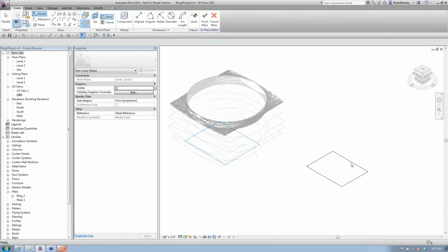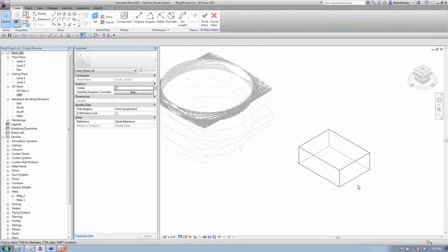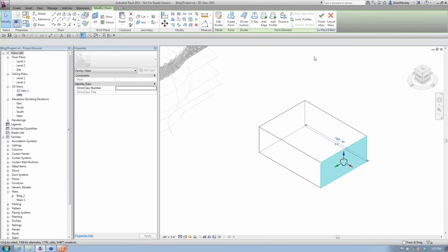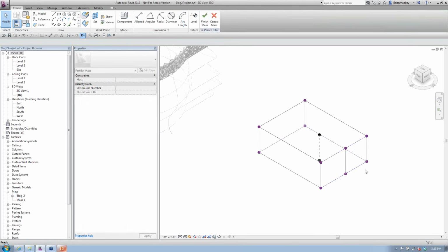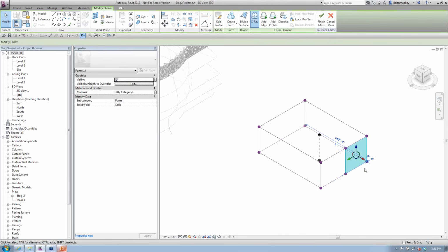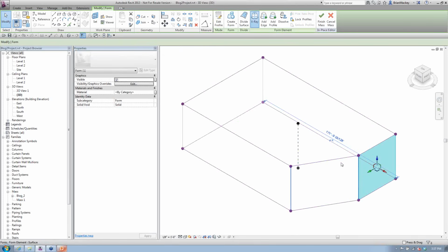So Vasari does have a couple other tools besides just what I'm going to show you. Like in Vasari, you can also work in camera view, so you can work in a perspective view, which we can't do inside of Revit, so it's got a tool there. But there's one you have in Revit that's called Add Edge. And if you go back and select a face in Vasari, if you hit the space bar, it'll change this icon, because right now when I pull this face, this edge comes along with it. In Vasari, when you hit that space bar, it would have left that straight and created like a 90-degree angle there. So Vasari has a few other tips when you get into it that we don't have in Revit.